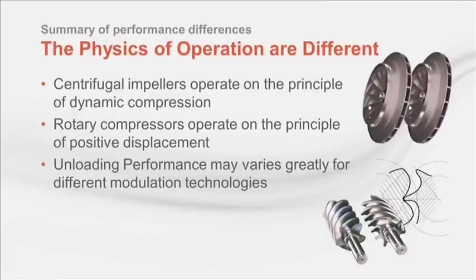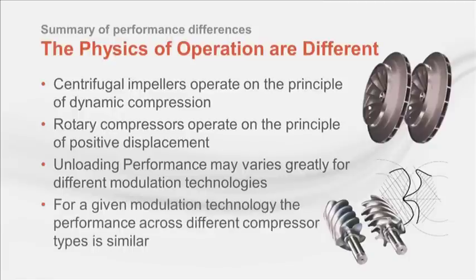However, for a given modulation technique, whether wasteful hot gas bypass, good mechanical modulation, or variable speed modulation, when you do an apples-to-apples comparison of any one modulation method on different compressors, the chiller's performance will look pretty similar for typical HVAC system operating conditions.